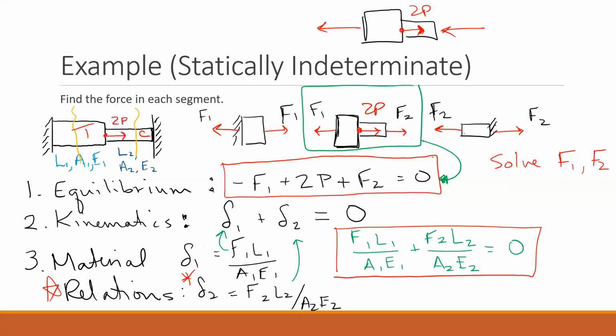You can imagine to yourself, say this one doesn't provide any resistance, then the full resistance comes from the right-hand side and has to be to the left. Same story. If the right-hand member didn't provide any resistance, it would all be from the left-hand side, and it would also be to the left. So therefore, when they act together, they're going to each provide some of that resistance, and it's going to be in the same direction that they would if they were working individually. So you can start here.